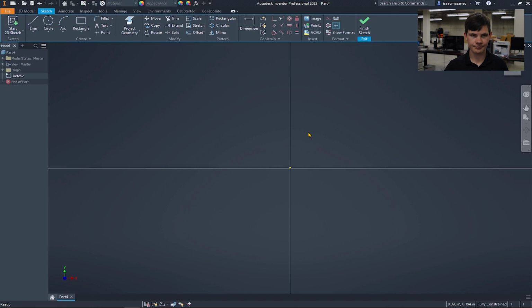I will be opening a new 2D sketch, and then we'll grab the calipers and open them. We'll take these here and leave some wiggle room so it can still slide in and out. Okay, so right here we have 113.30 millimeters. So what we'll do is click rectangle here, and then select it on the midpoint.